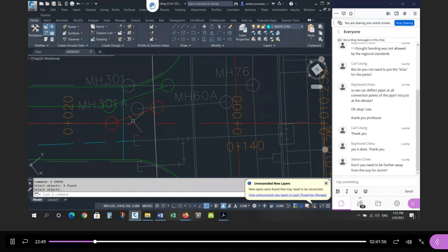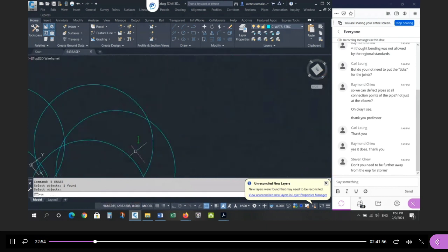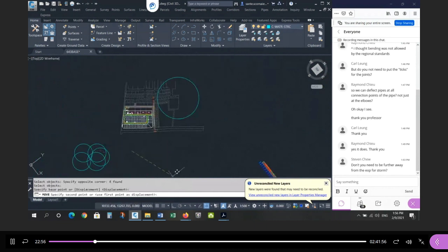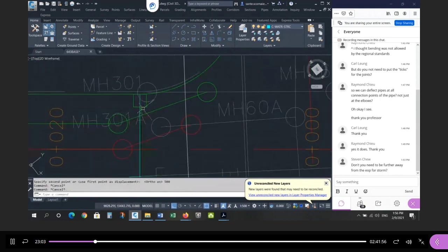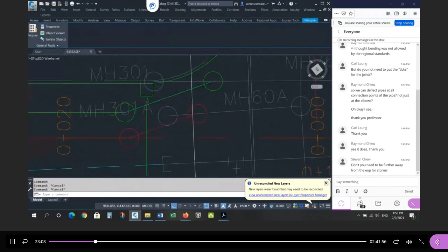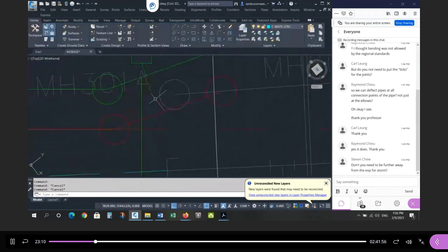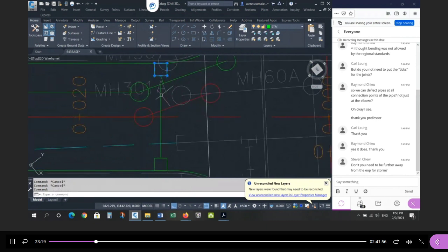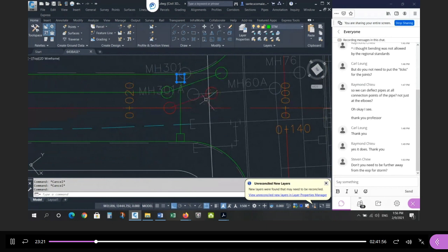Can I put in 2 catch basins and make all this plumbing work? Okay, well, so I drew a solution for that. So here's mine. Just moved it over for the sake of the discussion. So I can put in a catch basin and connect perpendicular to the pipe, and I can put in a catch basin and connect. It doesn't have to be perpendicular. I could use something different here. We'll talk about the details of that later, but I can make this connection. So the structure physically fits. It's tight, but it fits.